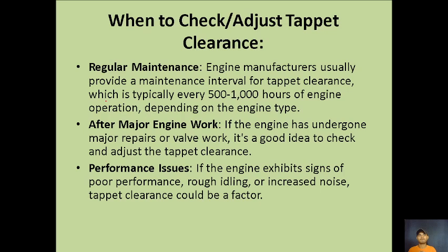So how will you check if your tappet clearance is now okay? We can listen using a screwdriver or a stethoscope, and then you listen to each cylinder. If it's not noisy, then it's all good. Compare the noise of every cylinder head. You can also use the indicator diagram to check if the exhaust valve is okay. So okay, that's it for tappet clearance.